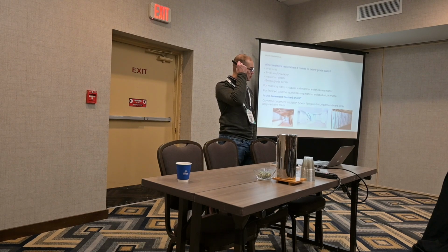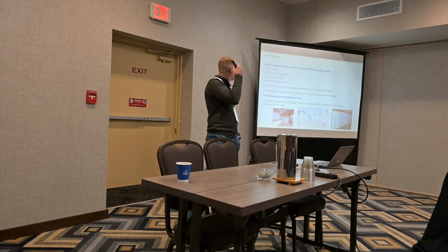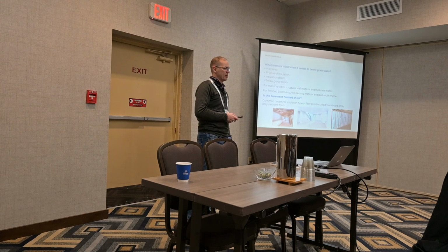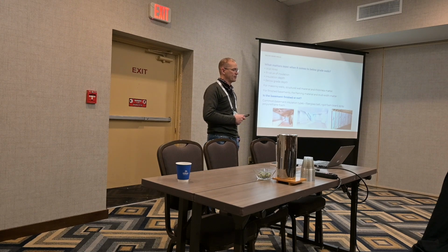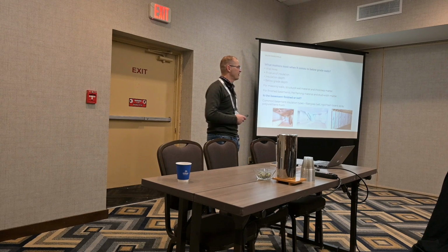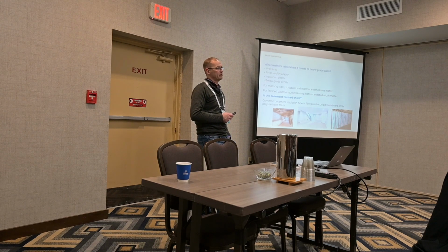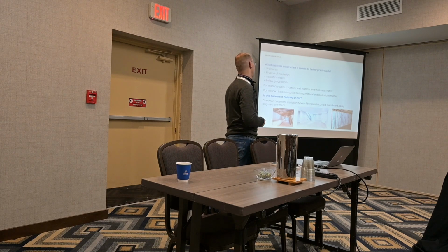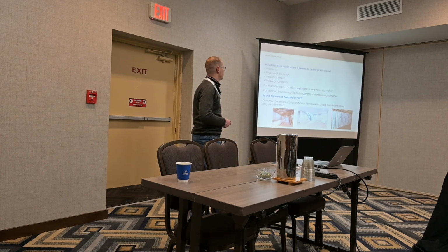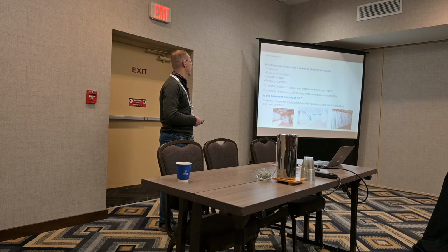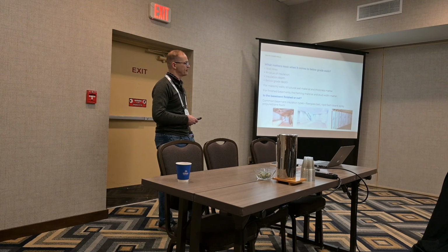Okay, so what matters most when it comes to the below grade walls? Same thing as above grade: wall area first, and then the R-value, insulation depth, and then below grade depth. Half a wall being above grade for a below grade building is going to provide some type of heat and cooling gains. So make sure you put that in correctly for if it's a split level or a full basement. And even on full basements, they may still have some parts sticking above ground.